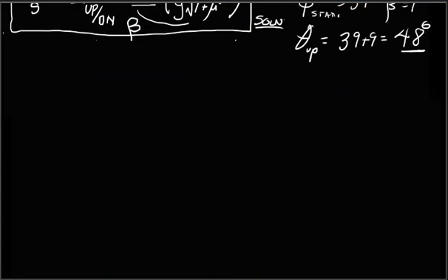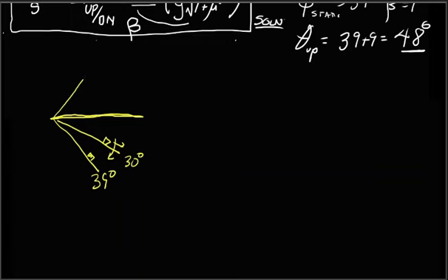And again, this should make sense if we look at that. Here's the 0 case. And on the way down, at 39 was the static. But we found that accelerating it caused the box to slip off sooner, at 30 degrees. On the way up, there would be a static case of 39. But we can go further past that now by 9 degrees, all the way out to 48.